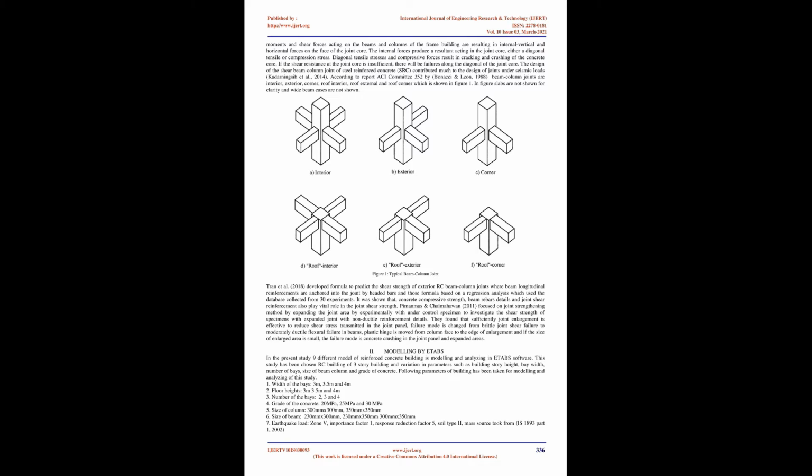Beam column joint is the zone of intersection of beams and columns, which is a critical zone in a moment resisting reinforced concrete frame. During ground shaking, large force acts on it, which has influence on structure response. For considering the effect of shear force developed on the joint, it is assumed to be rigid. When shear force exceeds the limit, shear failure occurs, which is always brittle in nature, and this failure is not an acceptable structural performance, especially in seismic conditions, so joints should have adequate strength and stiffness to resist the internal forces developed by the framing members.